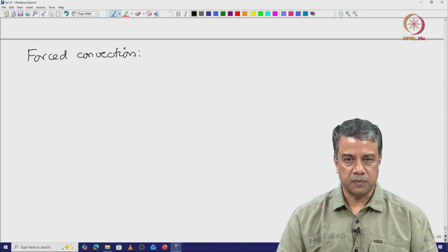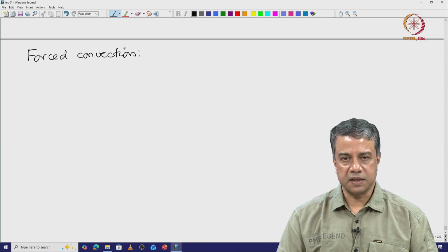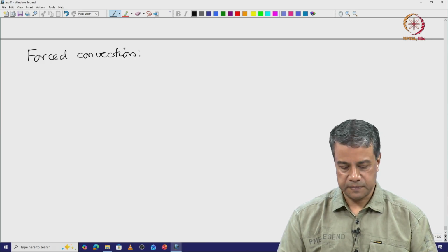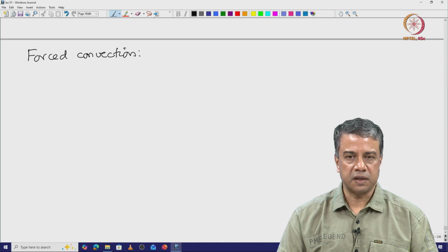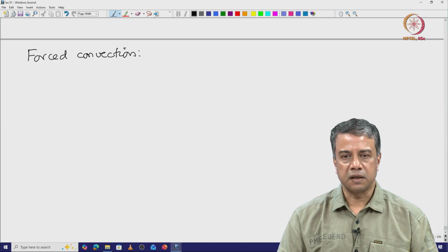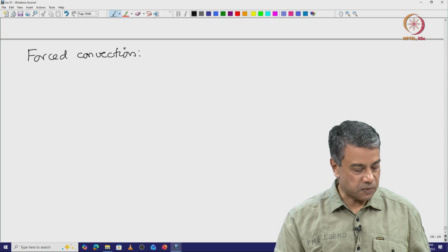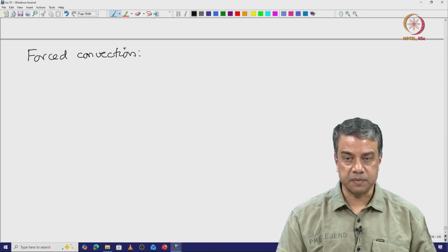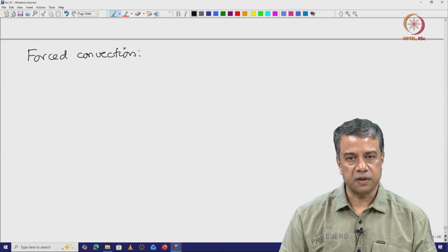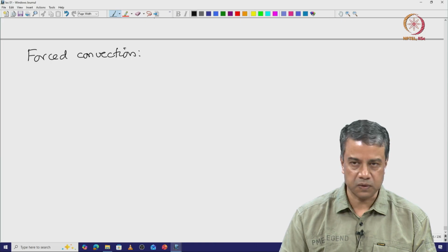The boundary layer thickness becomes small, and therefore, the heat flux, which scales as the temperature difference divided by the boundary layer thickness, becomes large. We saw that for heat transfer from a surface where there is a no slip condition at the surface, the boundary layer thickness scales as Peclet number to the minus 1/3 in the limit as the Peclet number becomes large, and therefore, the flux increases proportional to Peclet number to the 1/3.